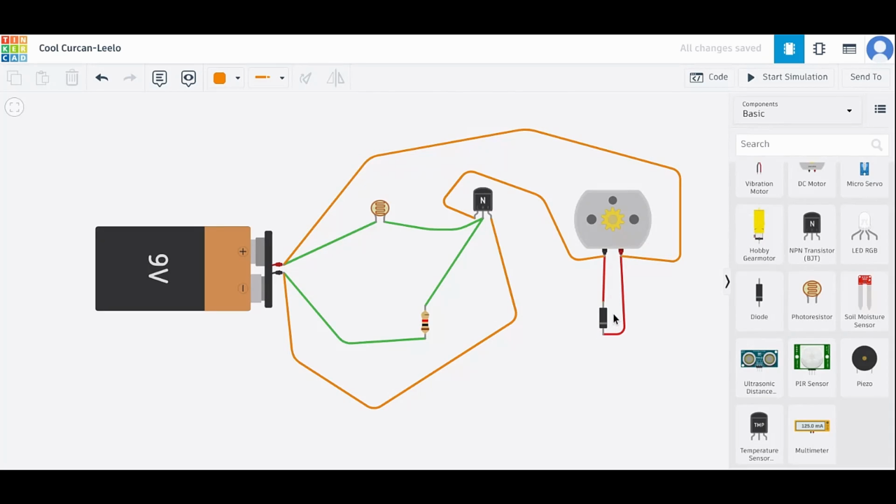Okay, we'll come to that part. Yeah, the diode prevents backflow of current. If you could see which way the flow is happening, it prevents backflow. That is fine. Current can flow back into the motor, no issue. But typically you don't want, at least in this case, the transistor to be affected.